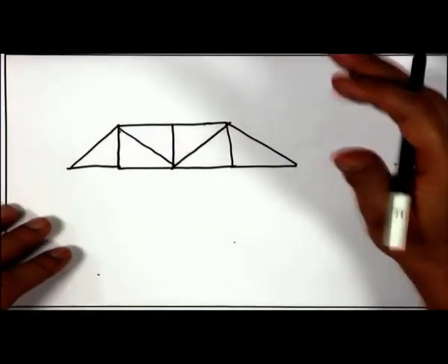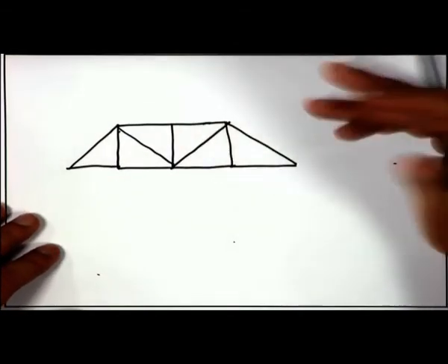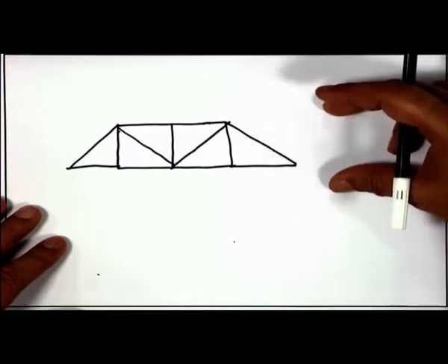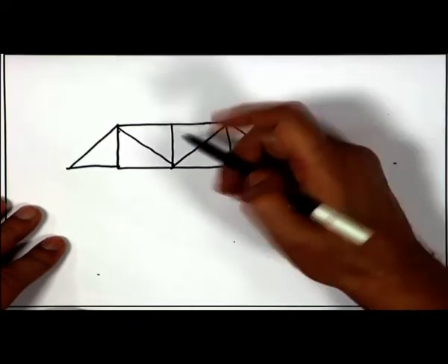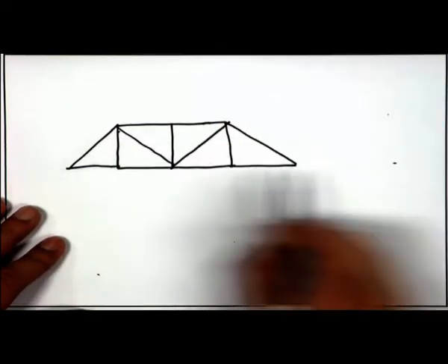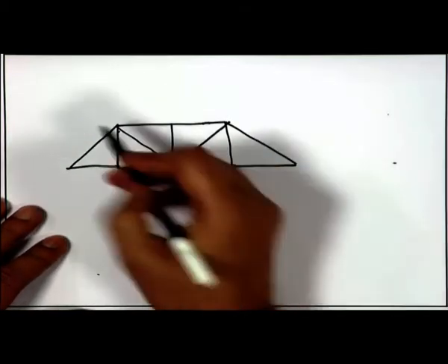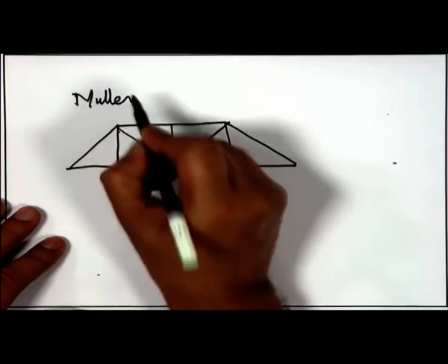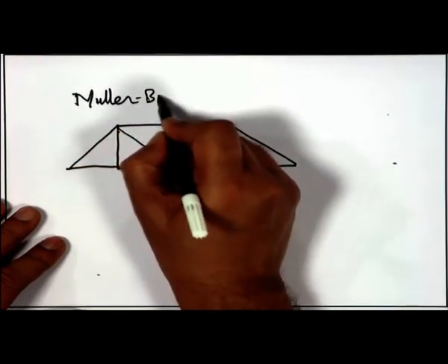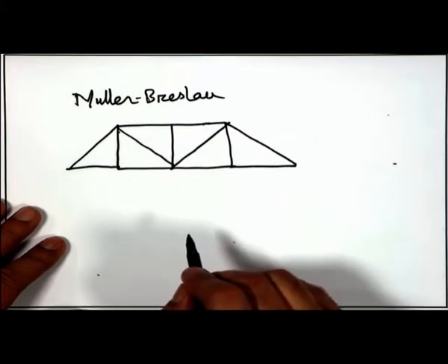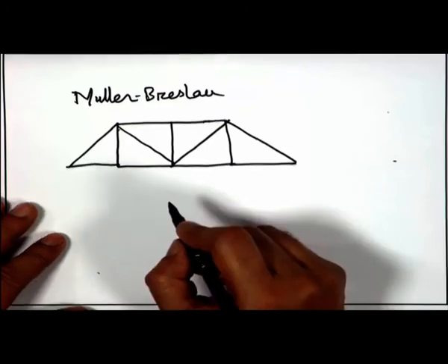We have influence line diagrams for the stress resultants. It works for the reactions, which are external. It works for the internal ones, the bending moment and the shear forces. So, it works for the axial forces also. If I am interested in plotting when a unit load moves on a structure which is a bridge, I will come to that later. Let us now only discuss the Muller-Breslau principle as it is applicable to other structures. Let me examine that carefully right now.